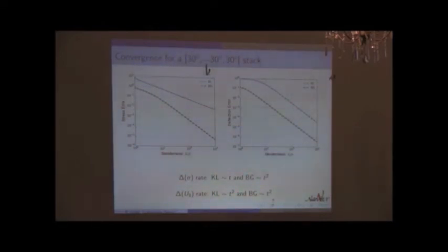This high convergence rate is observed because we don't have any boundary layer. The plate is not clamped. It is simply supported. I didn't say that previously, but for Kirchhoff-Love plate theory, there are convergence results which were well established. And it is established that when the plate is simply supported, you have this convergence rate. And when it is clamped, you don't have t squared, you have t to the 1/2. It is a very, very poor convergence rate.